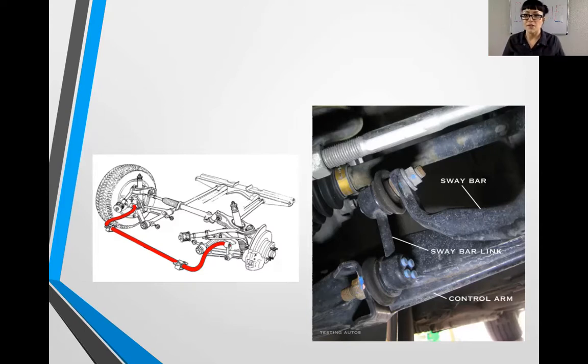Actually, my brother had a 97 Integra and said, man, this thing doesn't handle very well. And he doesn't take turns very aggressively at all, so I knew something was wrong. When I drove it, I heard a clunk every turn, and I got so much body roll. I instantly knew this was a sway bar problem. Sure enough, when I lifted up the vehicle, the sway bar end link was completely broken off. Quick fix, and it stiffened it right back up in the corners. So this actually does a really big job. You'll definitely notice it if the bushings or the joints are bad.